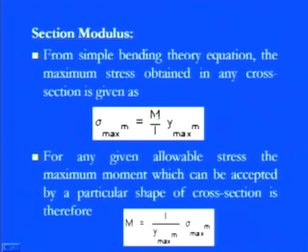whatever the bending moment which you are applying. I is nothing but the summation of y square dA. So these are constant, but the key feature is this distance y maximum. Means you see where this maximum bending stress is occurring, which fiber is experiencing this maximum bending stress, which can be easily calculated once you know the location, you can get the maximum value. So sigma maximum is basically depending on y maximum, that is the distance from the neutral axis. So sigma maximum is equals to M by I into y maximum.